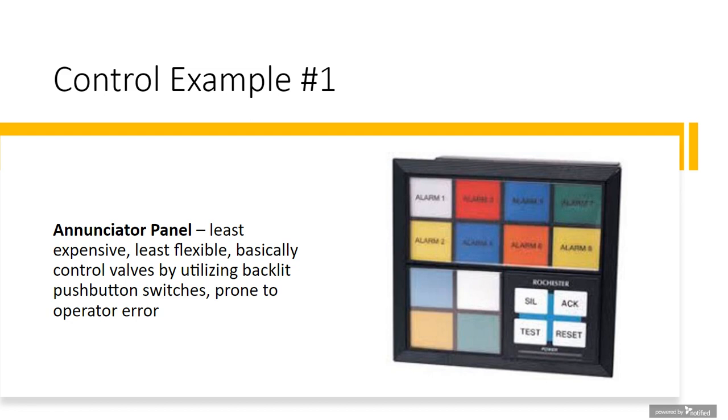So what you can see here is, although it's a very inexpensive device, if you're trying to do something like a thermal flush or thermal disinfection, you're going to be heavily dependent on the operator of these push buttons to make sure they're pushing the right buttons to effectively do the thermal disinfection. So very inexpensive. Every switch is wired to a solenoid valve, but very inflexible and prone to operator error.